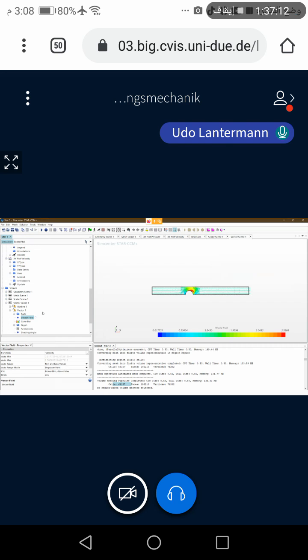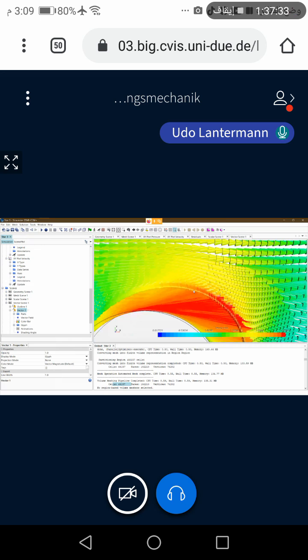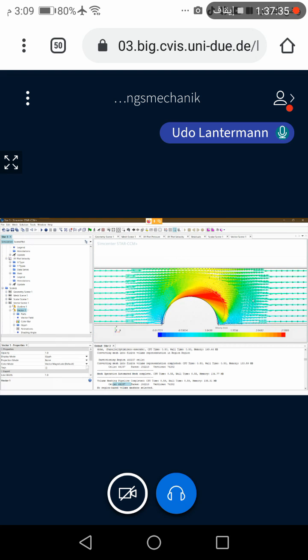But I didn't want to see vectors, I want to see this line integral convolution. This can be chosen by vector. And then there are different options. There is one display mode. If you want to see your velocity vectors, then choose this glyph. It looks like here. So you see some vectors for different cells. But I want to switch this one to the line integral convolution.